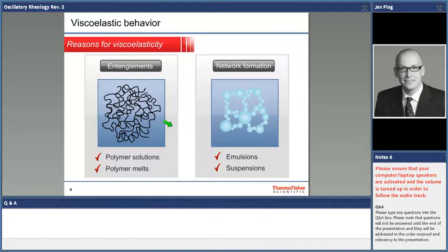Okay, you chew a chewing gum, you deform the chewing gum while you do so, and this deformation energy is stored elastically right in the polymer chains, okay, in your product. What's going to happen then is that after the deformation process, that energy is then used for back deformation, or we call it relaxation, okay, which for a chewing gum is something that you want to happen, because otherwise it would not be a chewing gum.